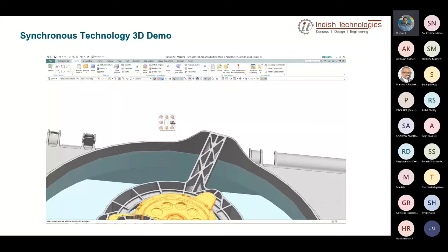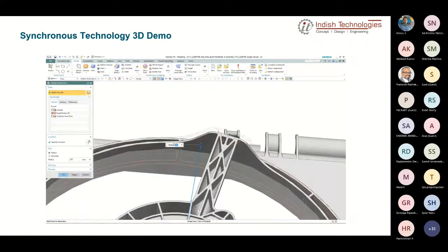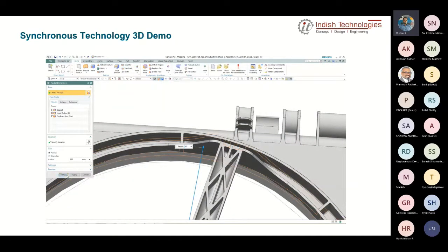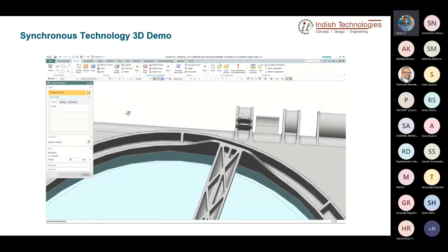So in this case, we'll use the radial dimension command, and we have different constraints or different selection options where we can find, say, coaxial faces that have to be moved together, or coplanar faces that have to be moved together. And finally, we get a dynamic preview once we enter the value, and then we can choose to decide any modifications based on that.